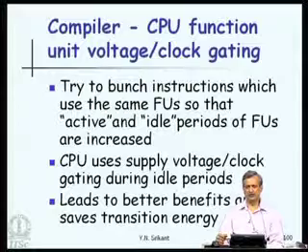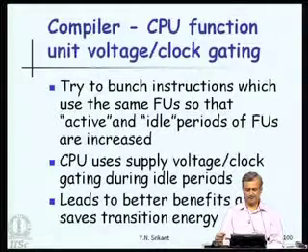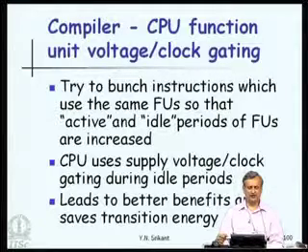The instruction scheduler brought them together. So, the ALU now keeps itself busy as long as possible, that is as long as there is no dependency on the next instruction and it is forced to wait. Assuming that there was an idle period between consecutive 2 instructions, now there will be no idle period between these 2 instructions.